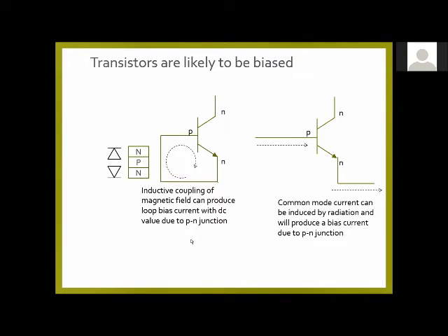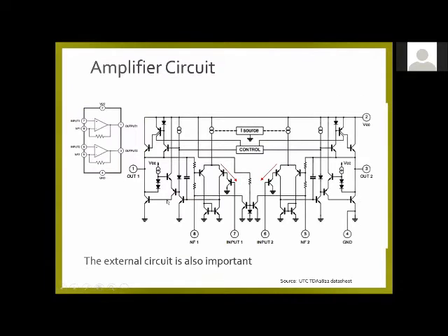Usually, besides diodes, bipolar transistors are likely to be places where that current will be rectified. If you examine the circuit of that particular amplifier, it's an IC, and the input amplification circuit has these NPN transistors, and there is a path where current can flow through those, but you have to know what's on the rest of the circuit, where the path would be, to know how to deal with it.